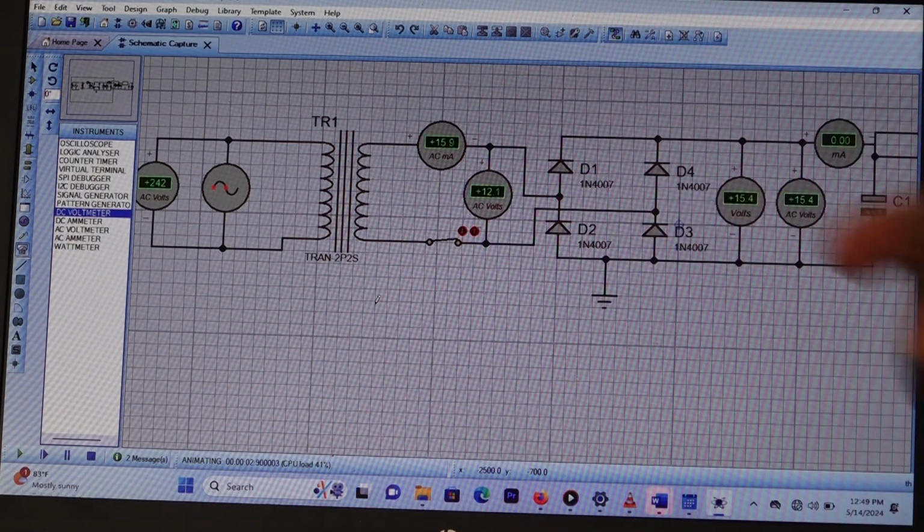And then what do you see? Once we have the voltage regulator, the filter unit, and the bridge rectifier, when you check the measured output current of the step-down transformer, it's what? 15.9 milliampere. Previously, if you do remember, it was 0 milliampere.